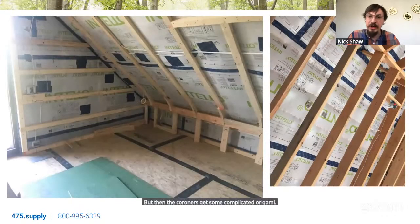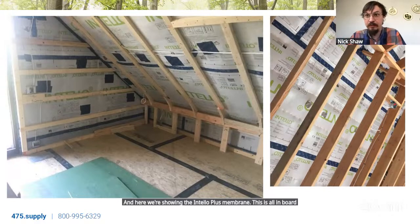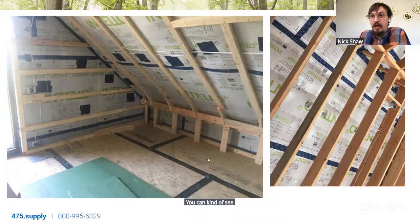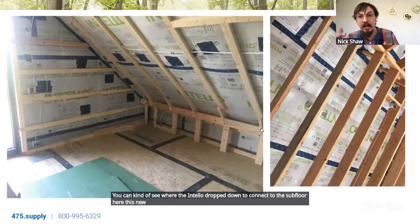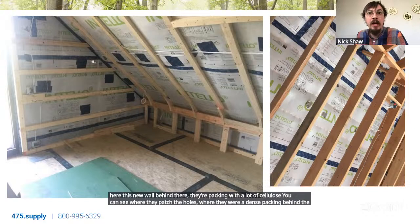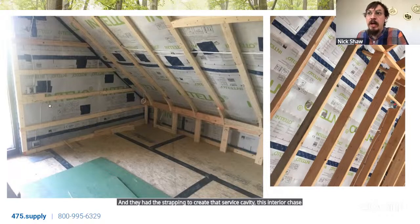And here we're showing the Intello Plus membrane. This is all inboard of our insulation for the roof. You can kind of see where the Intello dropped down to connect to the subfloor here. This knee wall behind there, they're packing with a lot of cellulose. You can see where they patched the holes where they were dense packing behind this Intello Plus membrane. And they had the strapping to create that service cavity, this interior chase for their outlets.